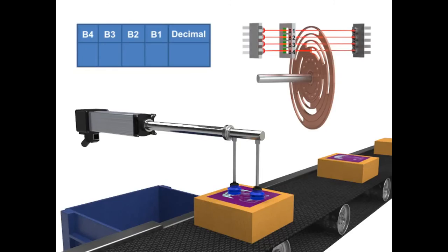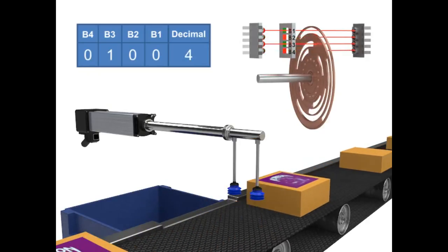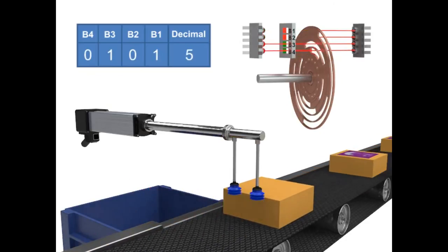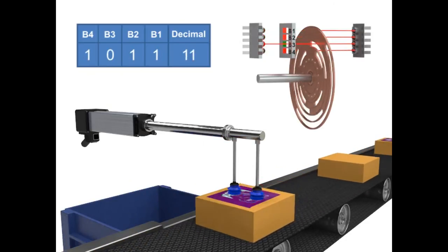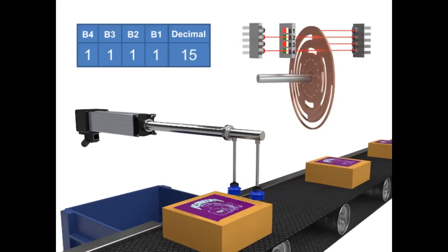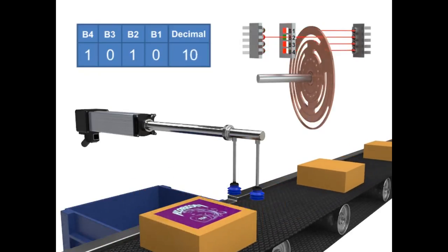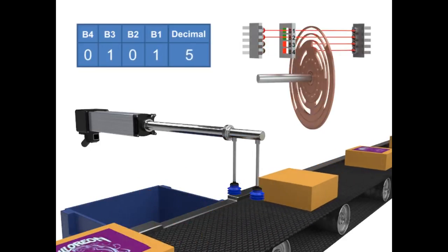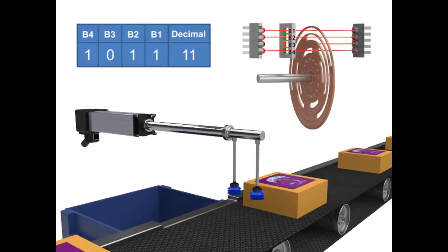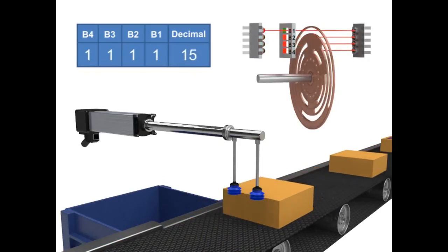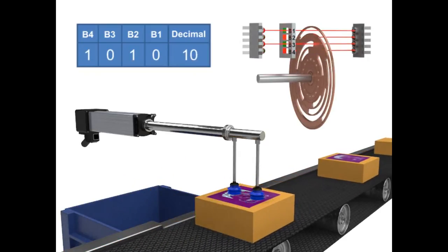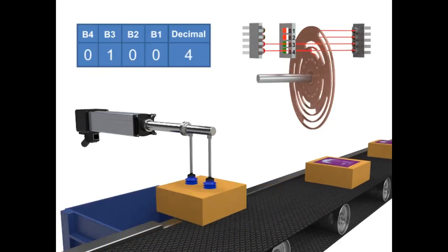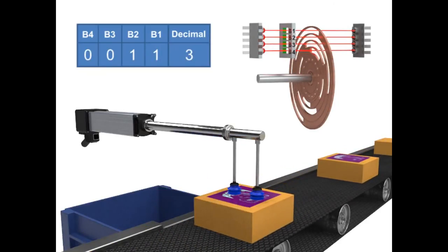For robot applications, absolute encoders are commonly used for precise positioning operations. The actuator in this example demonstrates the function of the absolute encoder in operation. As the actuator moves to push the carton, the encoder provides feedback that it has reached the user-defined position. The actuator then moves back to the home position, verified by the encoder, and completing the cycle. Using feedback devices closes the loop in motion control systems.